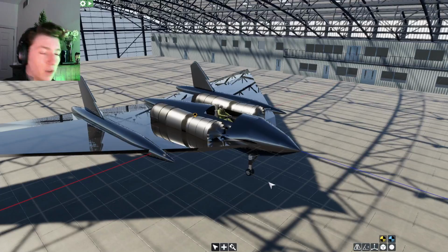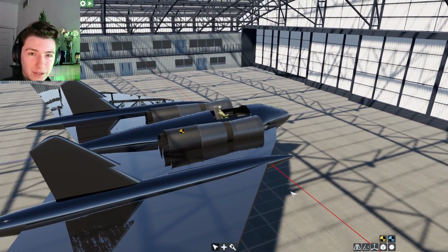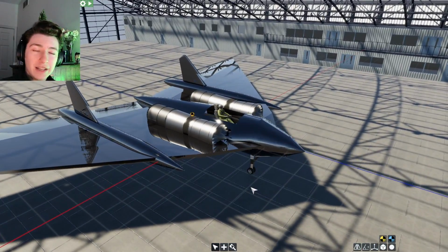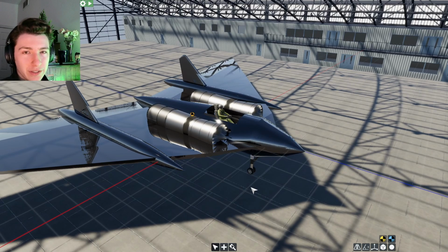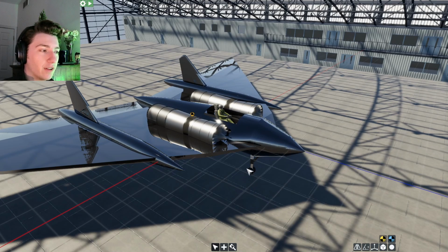But anyway, one additional note before we start the actual process: a fly-by-wire system can also be useful on a stable aircraft. It can actually just help you to control the aircraft more accurately. So while these are needed for unstable or conventionally unstable aircraft, they're also helpful on other, normal types. You don't only need to use them for these sorts of crafts.